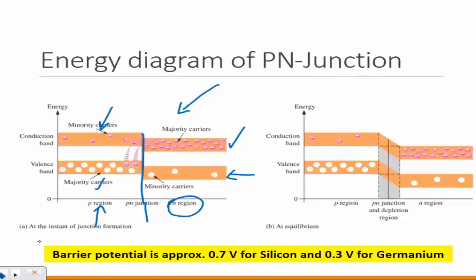So there's probably a better way to make it 0.6, 0.5, to change that barrier potential, right? If you run them in series, it goes 0.5, it gets one circuit, 0.6, it's going to be another. Yeah, there are some applications where you place them in series. There are some applications that you can put 2 diodes, 3 diodes back to back to achieve something else.